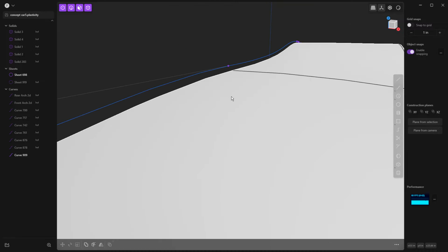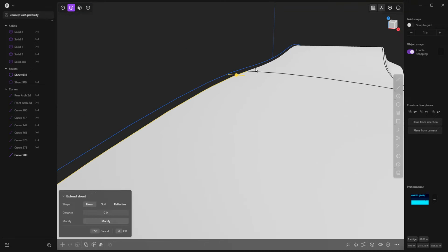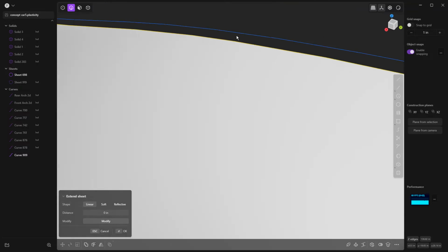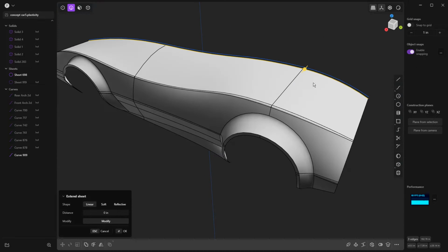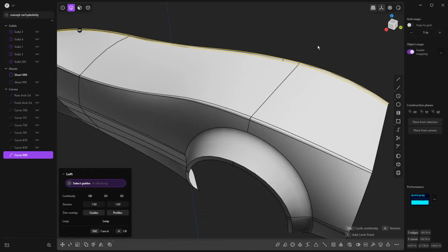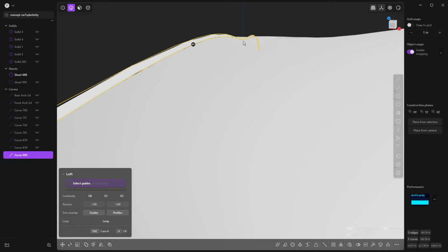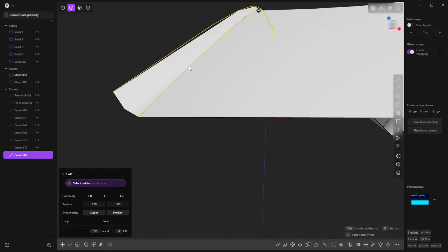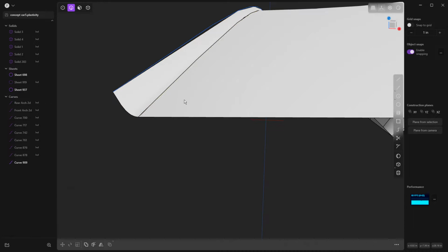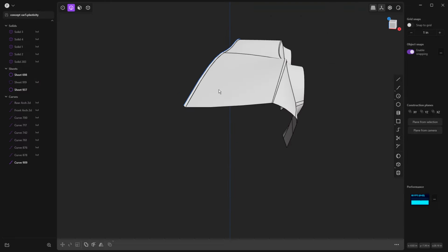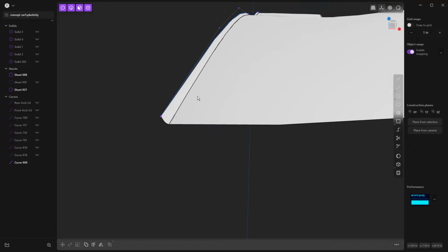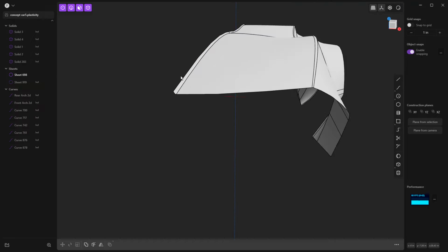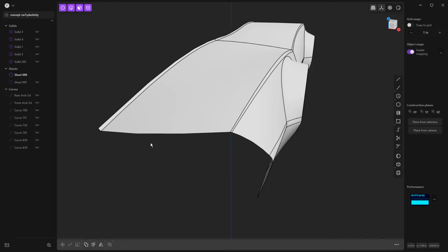All right, so now go back to our edge selection. We're going to select all the edges on the surface. Make sure that we have them all. We're going to select this, and we're going to loft to it. Now, when we loft to it, it should have G1 continuity here. We'll right-click and accept. And then go back to our all selection. Join this together, so J on the keyboard. Get rid of that line in the middle. Now, that edge is probably a bit extreme, but once we add a fillet to it, it's going to sort of dull it down a little bit.